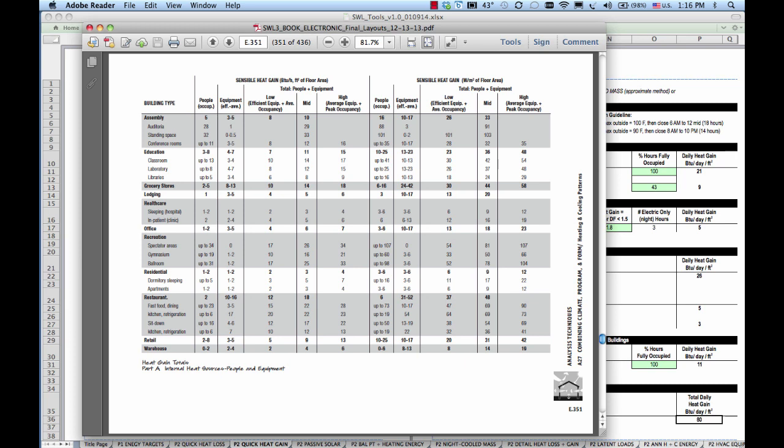Now be careful here. In some occupancies, equipment loads are rising rapidly. In others, the actual occupant density may not be what is assumed. You can also use the occupancy heat gain analysis technique A16 to find the heat gain rate if you already know about how many people will occupy the building or zone that you're analyzing.